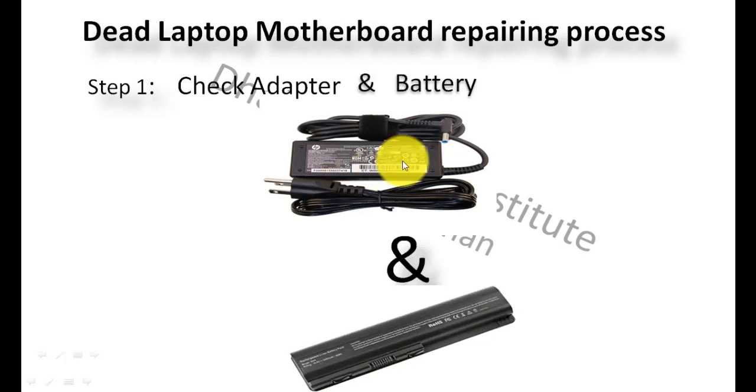Secondly, check your battery by unplugging it from laptop and insert good or okay adapter and see does the laptop open or not, because battery sometimes also can be reason for laptop's dead problem. If you find adapter and battery okay, then you can be sure that it is laptop's motherboard fault.